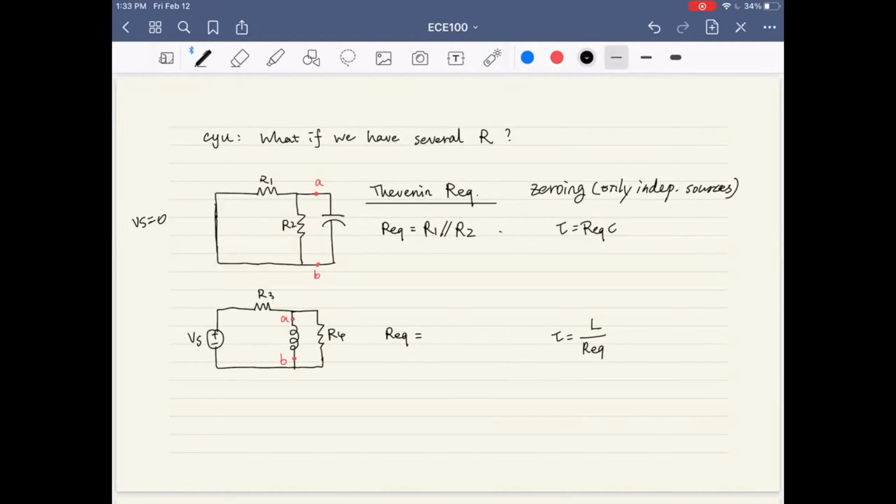After you get your resistance, compute the new tau with R equivalent times C. So the XC terms, if you need them, should be t over this tau. So you'll see that all the resistances and the relationship between them are reflected in the tau already, right? Because if they are in series, the tau will be different.